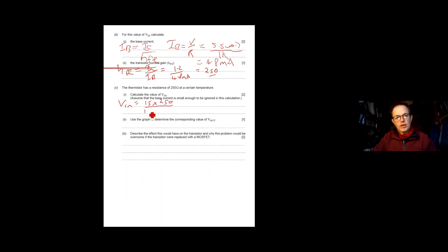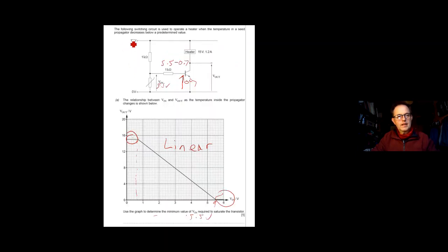And that's going to be over the 1,000 plus the 2,000, sorry, 250. Okay, just looking back where those numbers have come from. Right. There's a supply voltage. This happened to be 250. So it's that times the bottom resistor over the sum of the two. There's your potential divider.